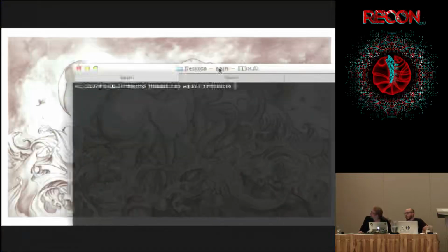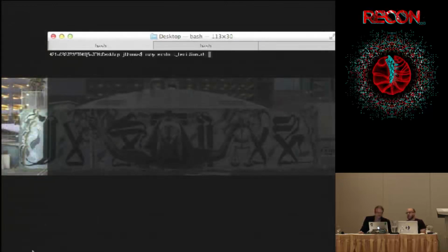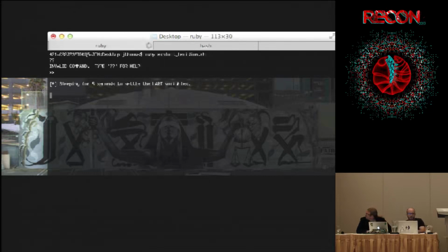This particular one, I was working on the shellcode last night, and the state at the time of the function call is where the banks are in a weird state, so the things that I want to call are in the wrong bank, and I can't yet get it all set up correctly so it doesn't just crash. So we don't have a cool flashy demo, but it's obvious that we're modifying flash memory like you're not supposed to, and then we're able to jump to it. So, yep.